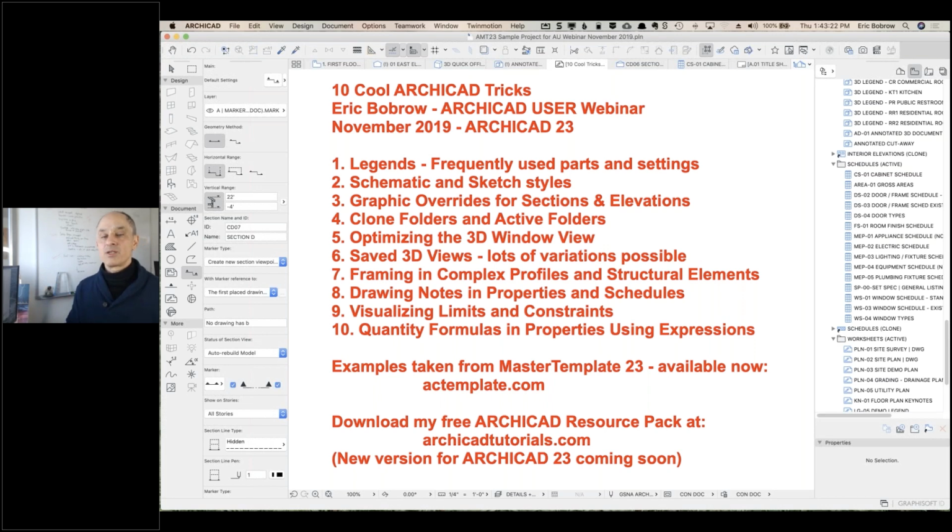One other thing that you can do in legends that you cannot do with favorites is you can have groups of elements, like an entire office or kitchen or bathroom or some landscape elements. You can select it from the legend, copy it, and paste it into your project as a starting point for quickly laying out the kitchen or something else. So with favorites, you can only do one at a time. So that's why legends have a unique place in my workflow.